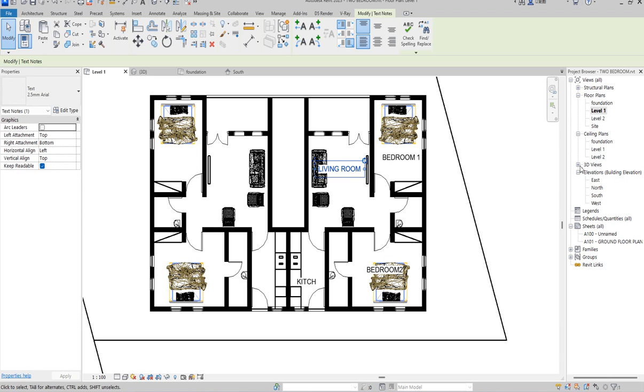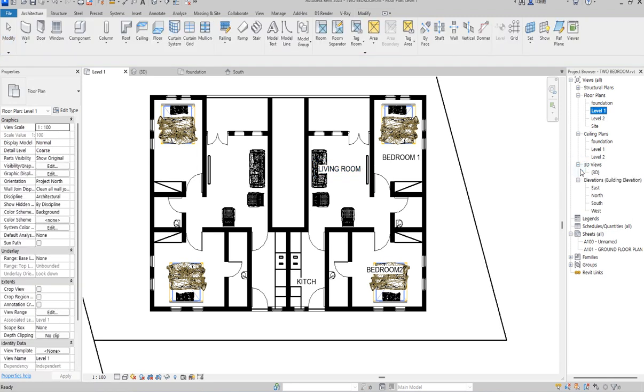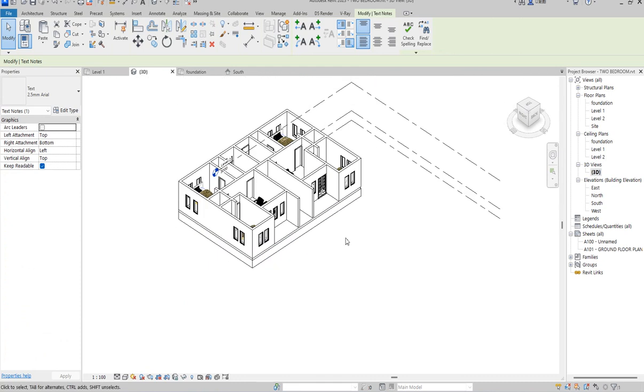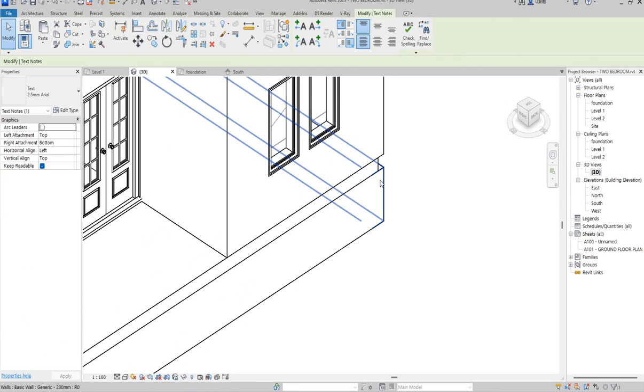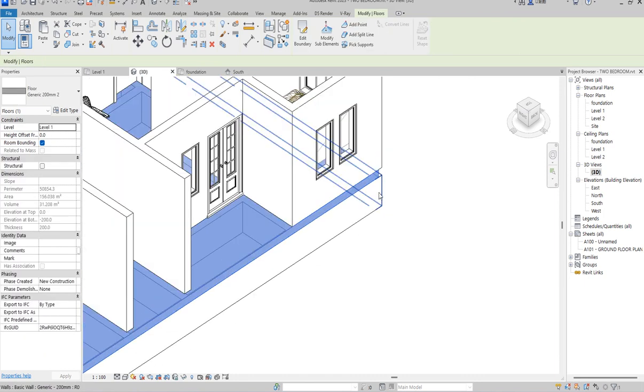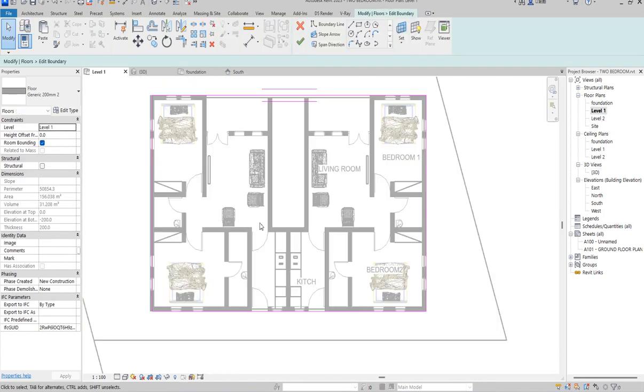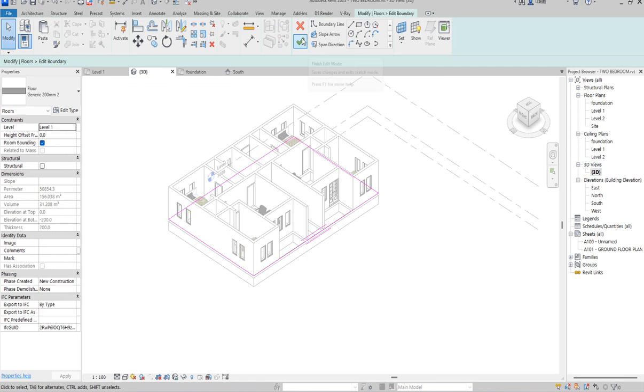So now when you go back to 3D and you see what we've done, you see that the foundation part is now available. So you can edit your slab and get to the main position. So where do we have it from? Here. So you just align it and the whole thing is done. So go back to 3D and click finish.